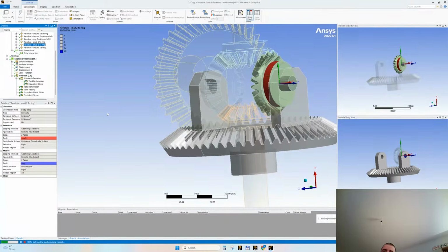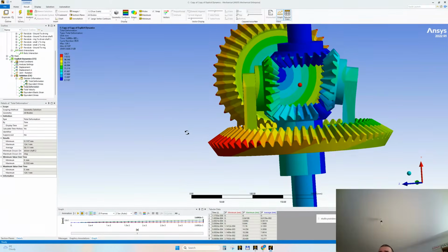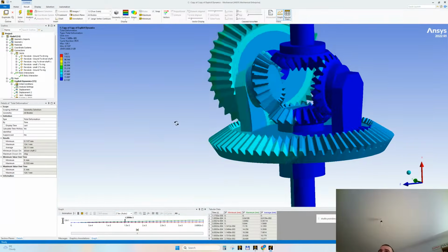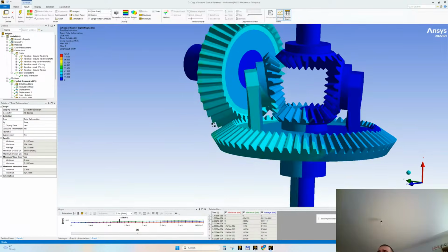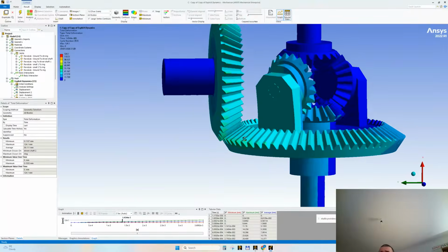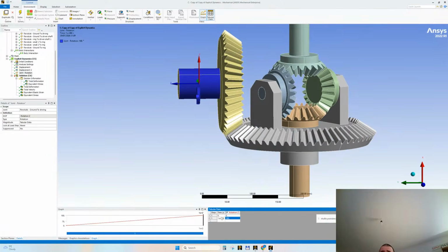You know what? We already have a frictionless contact here due to the body interaction. So I propose to suppress this body by the Revolute joint. So let me animate, to tell you what is my purpose here. So I said animate. Oh my god. I think I need to engage smoother. It's a sudden shock here, 180 degrees for this 10 milliseconds. It's pretty harsh.